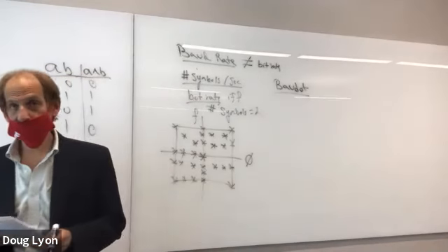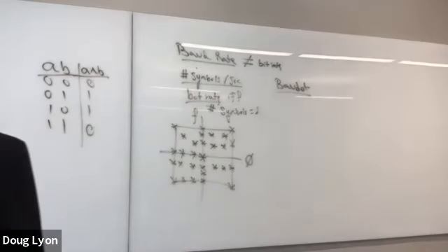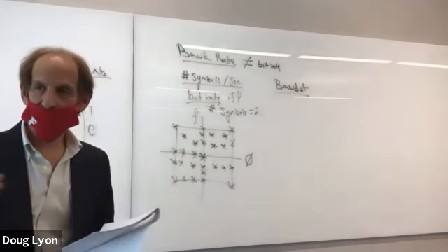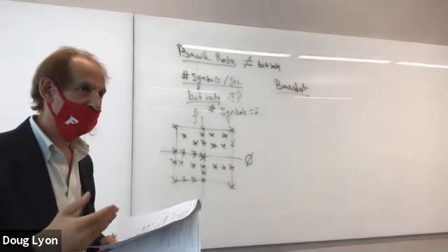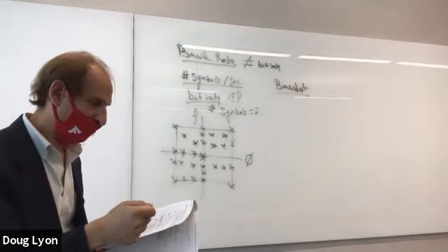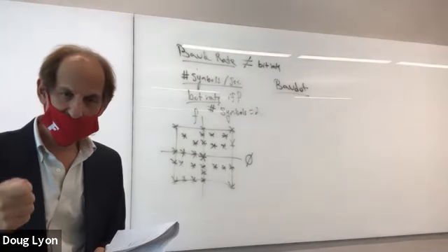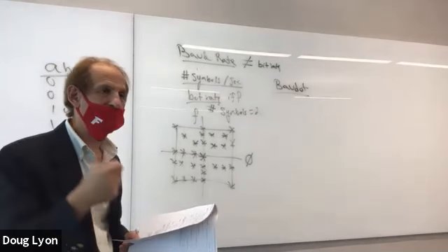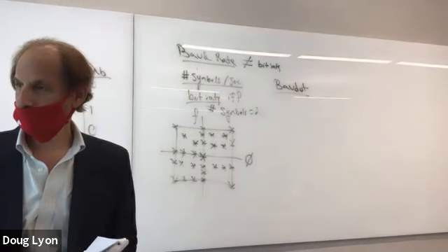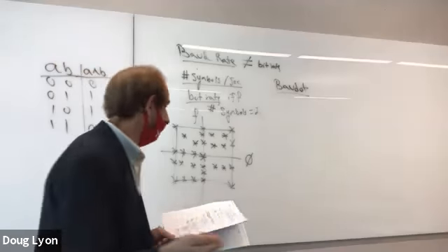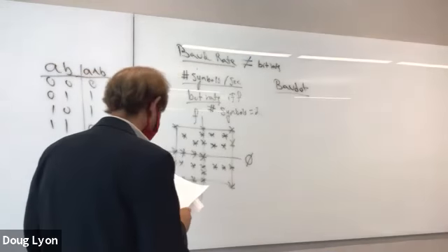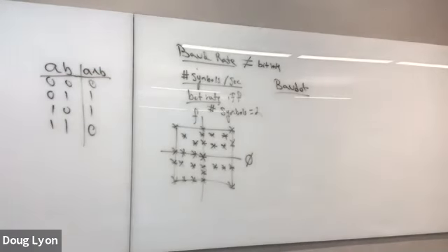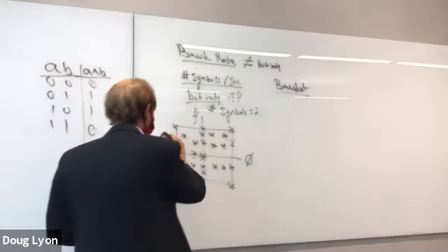Serial communications is very important for microcontrollers because they need to have a way to talk to the sensors and to talk to other computers. So for example, when you plug the USB interface of your Arduino into the USB port on your computer, it's using a serial communication protocol. In fact, what it's doing is simulating a serial port that uses what's known as asynchronous communications.